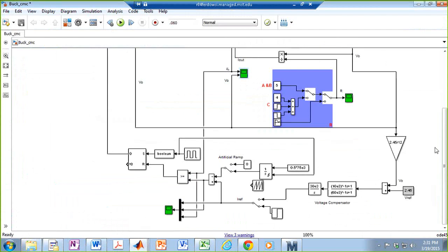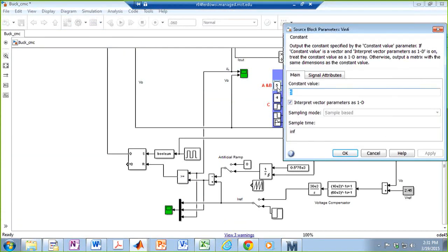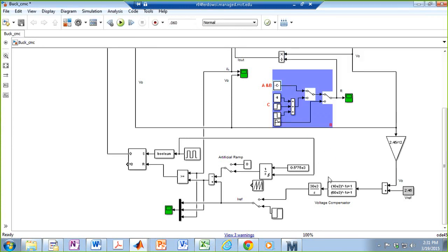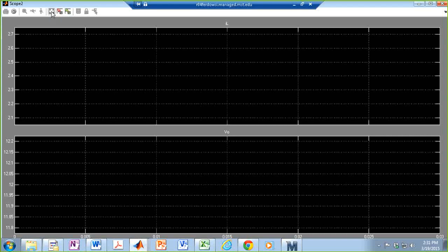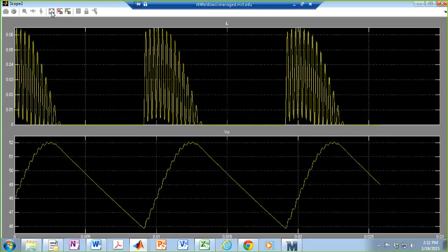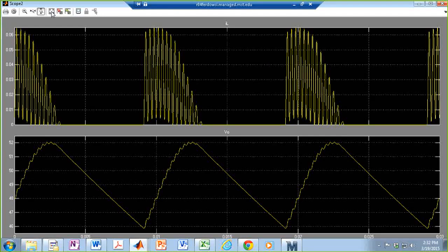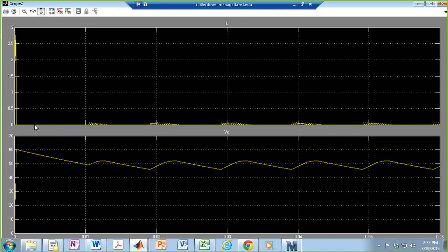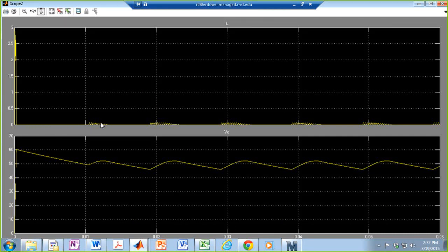Okay, let's see. Let's have a very, very small load, for instance, 5,000 ohms. Almost open circuit. And then I'm forcing the inductor current to be 3 amps. So you can see on average my output voltage is almost 48, which is the input voltage. System is kind of in DCM. It's kind of chaotic, and basically I don't have any inductor current at all.